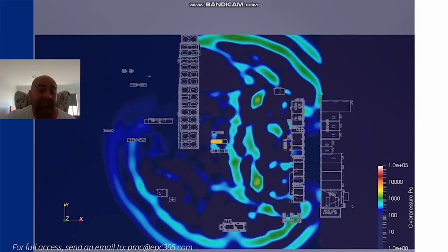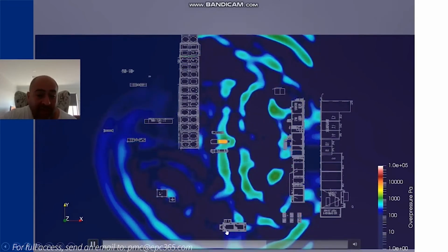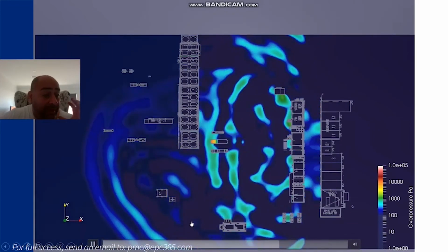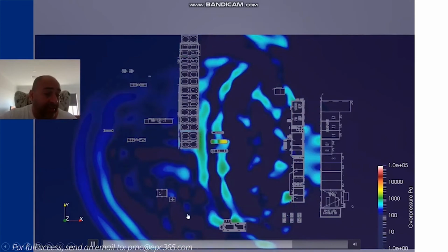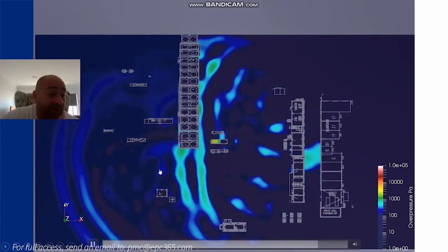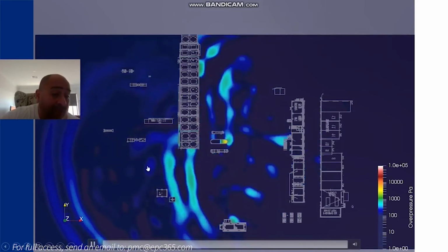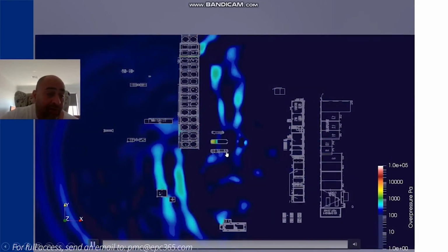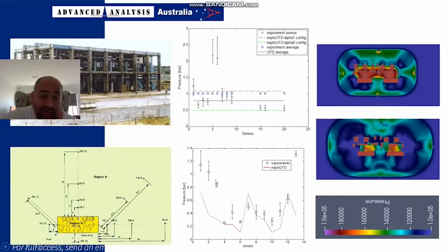But on top of that, the released chemical may be ignited, and Xplo CFD is the only software that actually models that as well. It could make a very big difference in terms of overpressure. You could go from half a bar to 10 bar if the tank were in a congested area and releasing a high energy material. We've done a lot of validation on this.